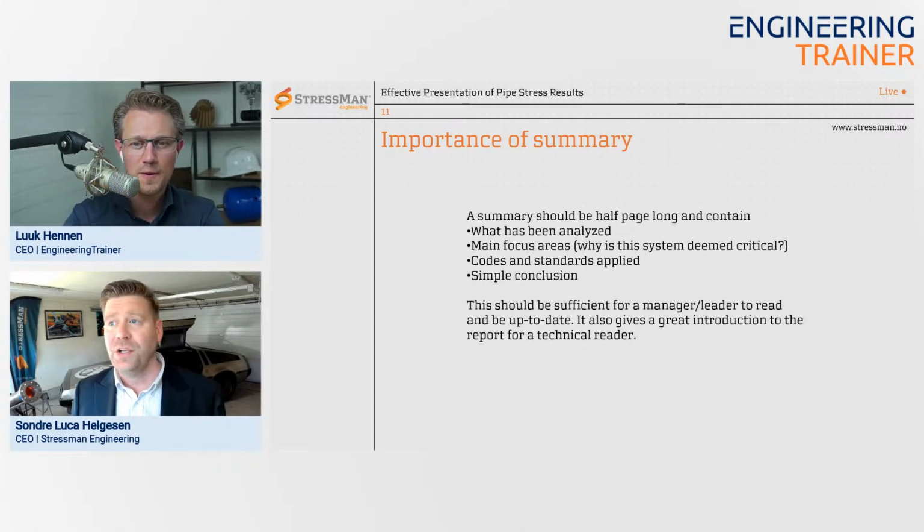And as you say, you might not have the data. I've been to oil rigs, old ones. I went out there and went into the high pressure mud pump room, looking around. It's like 1, 2, 3 pumps, okay, but my drawings are only showing 2 pumps, for example. Exactly. And then you look up at the roof. There is all the piping, and nah, let's throw those papers away and start sketching them up again. So then literally starting to sketch up what's there.